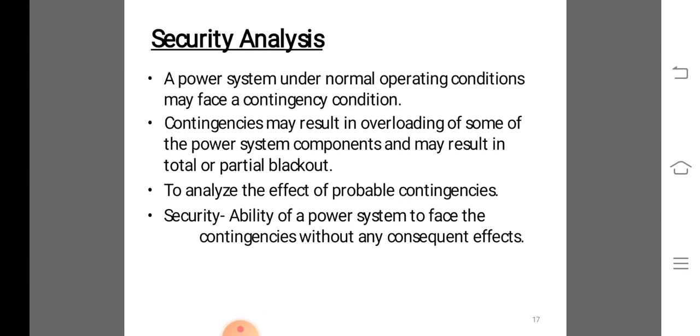The sequence means a sequential execution of programs that perform the following steps. One, determine the state of the system based on either current or postulated conditions. Second, process a list of contingencies to determine the consequence of each contingency on the system in its specified state. Third, determine preventive or corrective action for those contingencies which represent unacceptable risk.